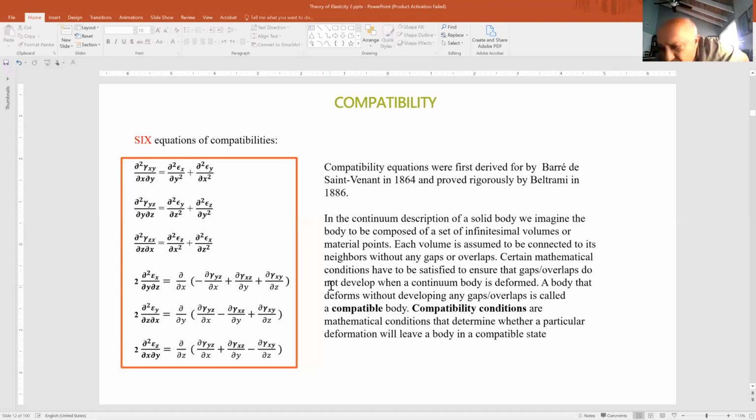By the way, most of the mechanics of materials problems that we solve in our undergraduate programs, theories of bending, theories for axial loading or torsion, are simply looking into equilibrium of the stresses and external forces. So we satisfy equilibrium conditions. We do not usually satisfy the compatibility equations.